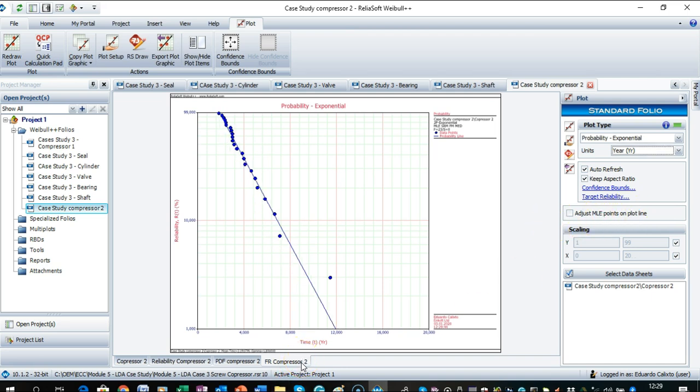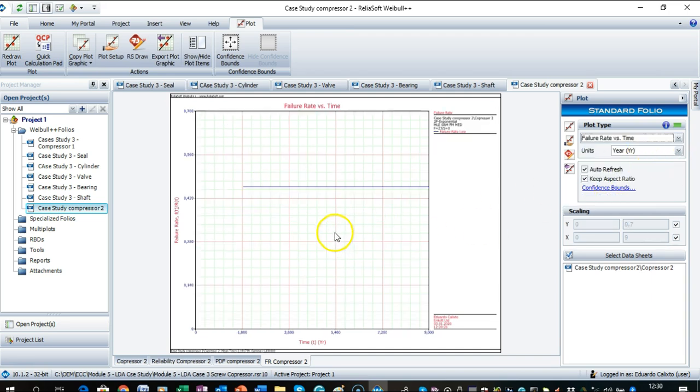if we want to take some decision about such equipment. If we use this PDF in a lifetime data analysis, in the run analysis to model a system, and put just the parameter of this exponential, that will in the end reflect the reality. We have this run of failures happening, and that will encompass the total number of failures that we have here for each pattern. But if I want to take some actions, look at the patterns of failure to have preventive actions to recover such components, I need to have data at component level. So here, just put the failure rate in years, and then you see the constant failure rate, and some 8.82 years the time that we do not have failure.